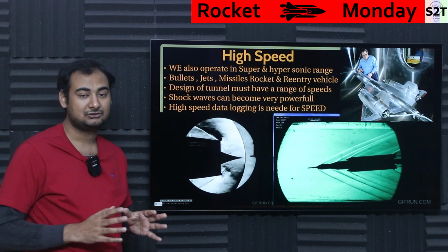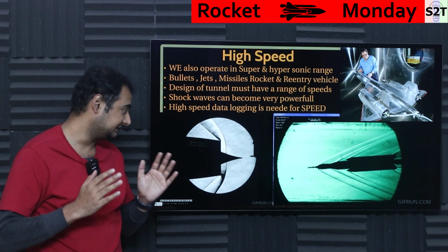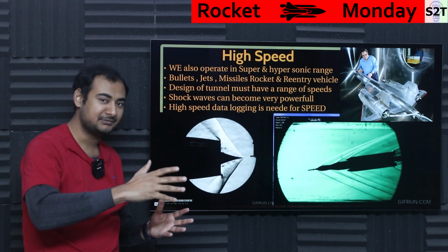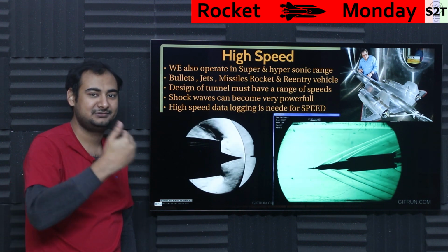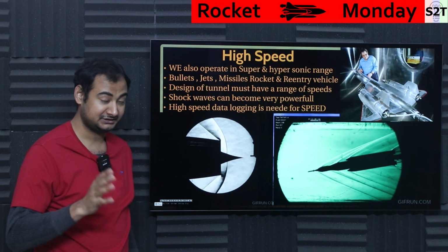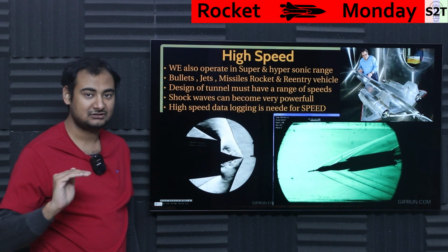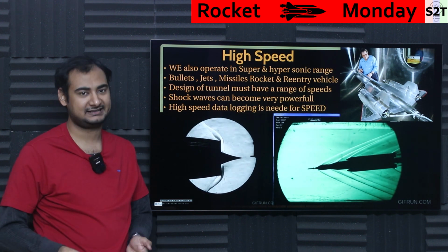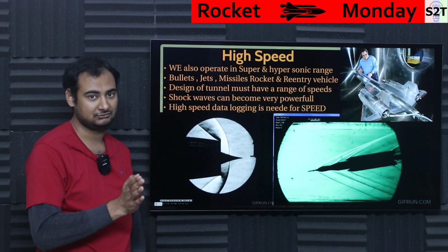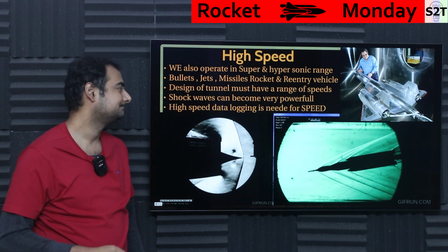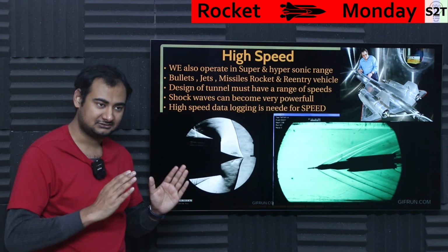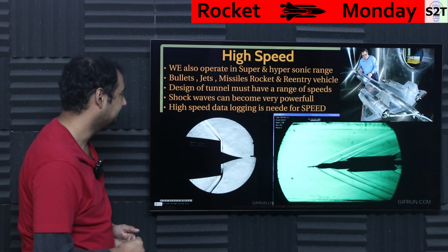Now you have to understand this core aspect of it: even if you take the SR-71, it's not like, okay, I take off the runway, I do refueling, voila, I'm at Mach 3. It's not a photon. It takes time to get up to speed. That means it crosses some regimes, meaning it couldn't go from subsonic to supersonic. That's a very naughty regime. And in those scenarios, you have to have a tunnel that simulates that, meaning it cannot be like, I turn on the tunnel and it's Mach 3. No, it has to slowly go through that. Ideally, you should be able to control that. So if you're designing a tunnel, you cannot just say Mach speed. You have to ramp it up. All that does matter.